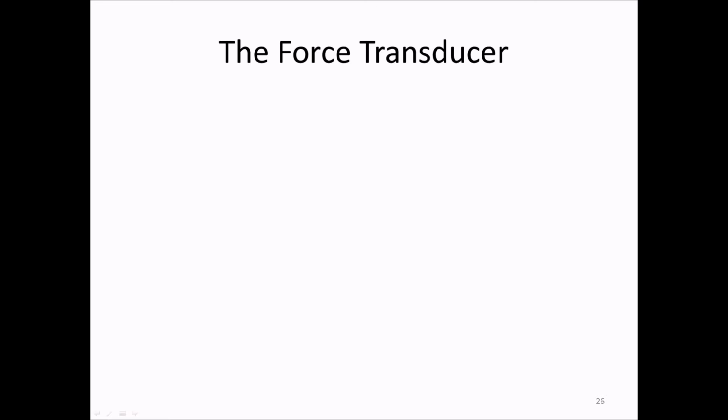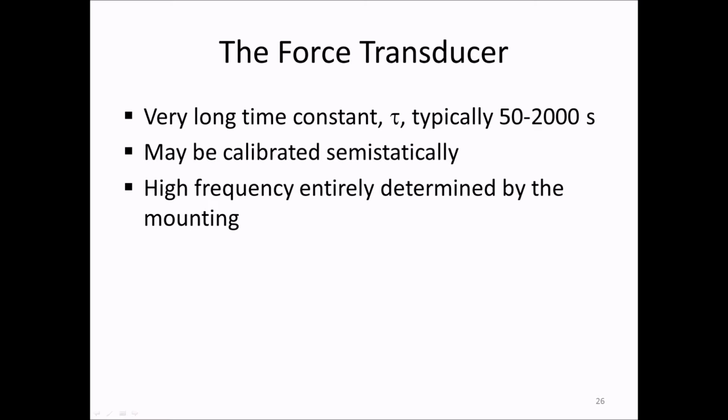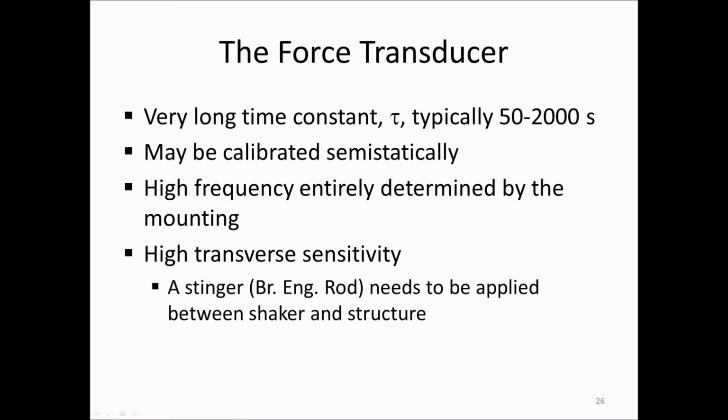Force sensors are typically designed with very long time constants. This is so that they can be calibrated semi-statically. Force sensors are also very stiff, so the high frequency limit is entirely determined by the mounting. A large drawback with the force sensor is that it's very sensitive to transverse vibrations.